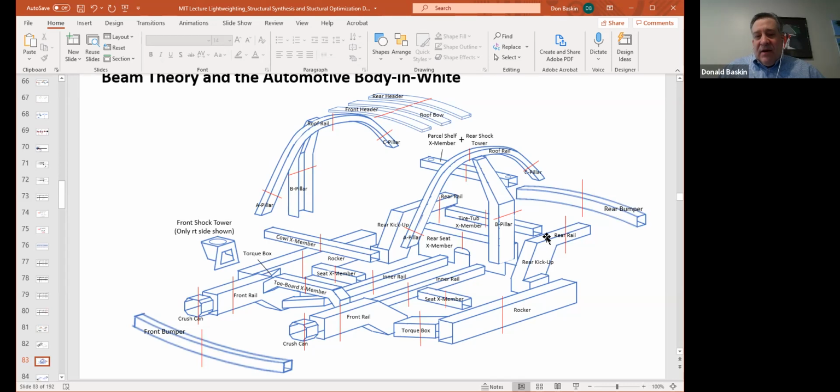The thing to think about here is that when you're just driving your car on a normal day, when you're not getting into an accident, which hopefully is 100% of days, the highest stress portions of the car are really the shock towers and where the load feeds in from the road from the suspension. Those are the areas that need to be most carefully designed so that there are no fatigue failures.